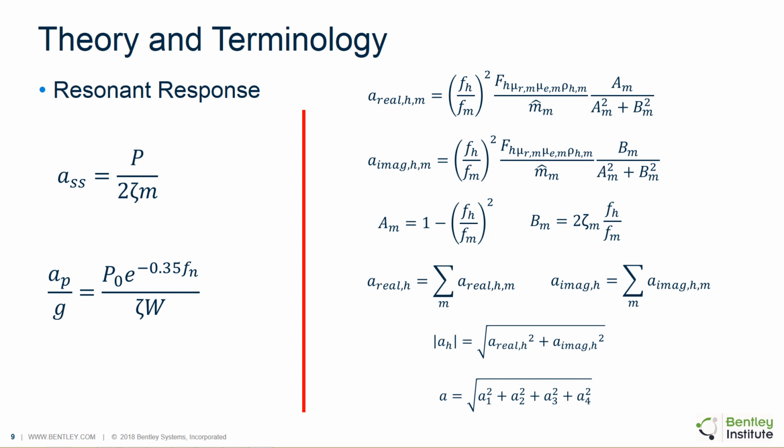So the r is the calculated response node or location, and the E is the excitation location. So we can actually calculate a response at a different location than we apply excitation. So this is a very flexible and robust closed form solution that we can use to solve irregular structures, where we're exciting the structure anywhere we want, and we can calculate the response anywhere else in the slab. And coincidentally, those can also be at the same point.